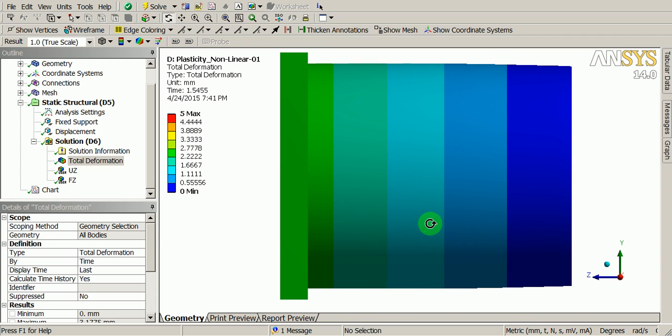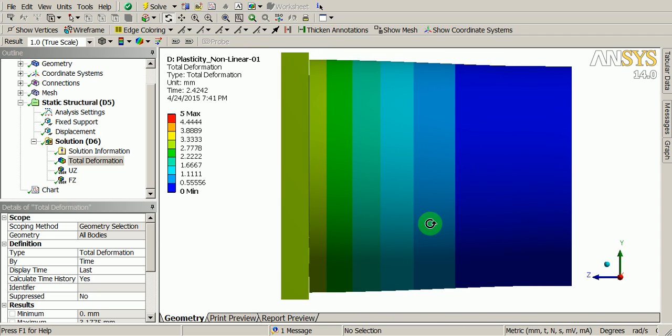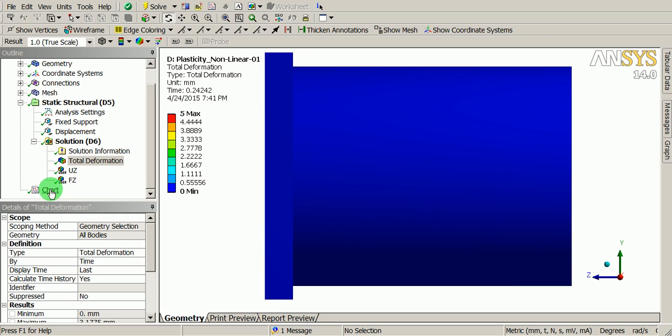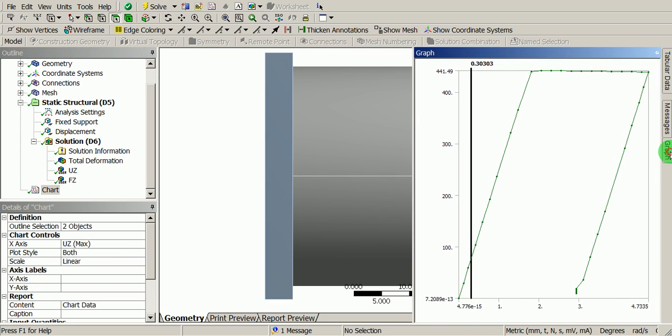And when we look at the force and deflection curve for this behavior, we can observe clearly under the graph that it has not followed the same path which it has to follow in the linear analysis. As we go on increasing the displacement, the reaction force started increasing. And when we started unloading the plate, at that time, the deformation was not 100% recovered.